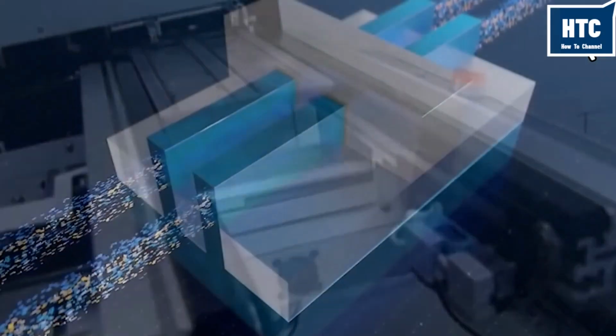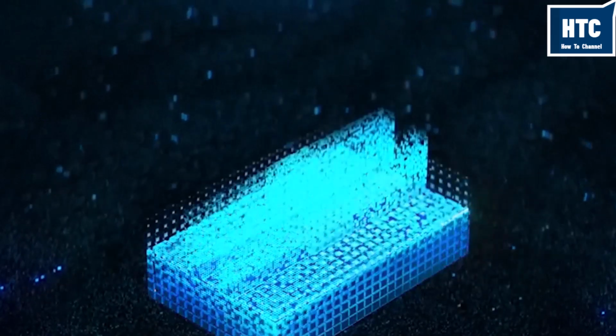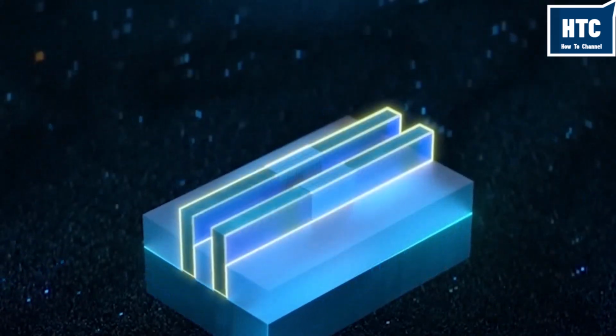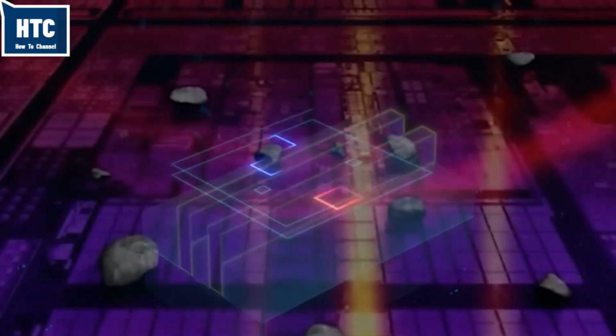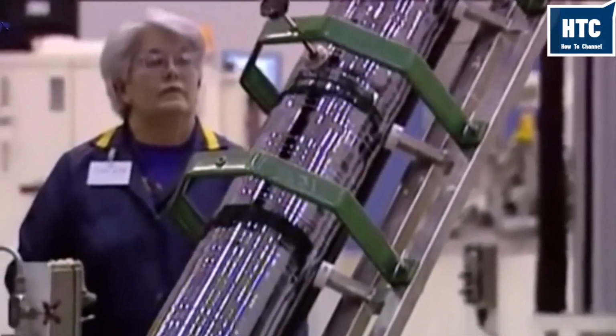Then, a thermal interface material, often a soft solder or thermal paste, is applied to the back of the silicon die. Finally, the integrated heat spreader, the silver nickel-plated copper lid, is glued on top. This lid protects the fragile silicon and provides a surface for the CPU cooler to sit on. But the manufacturing is done, the process isn't.